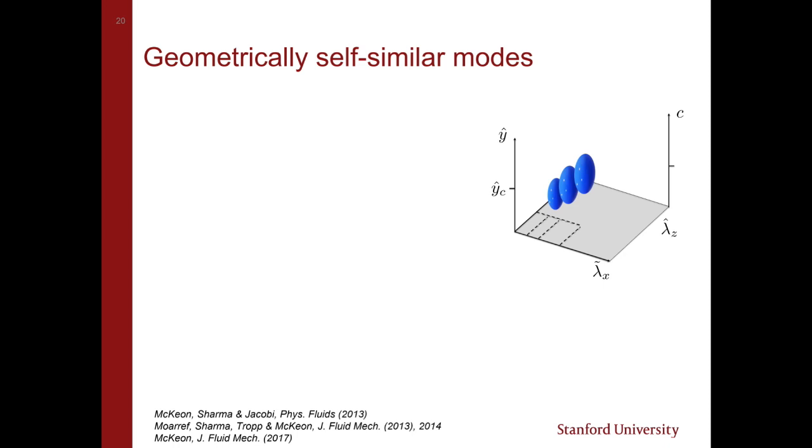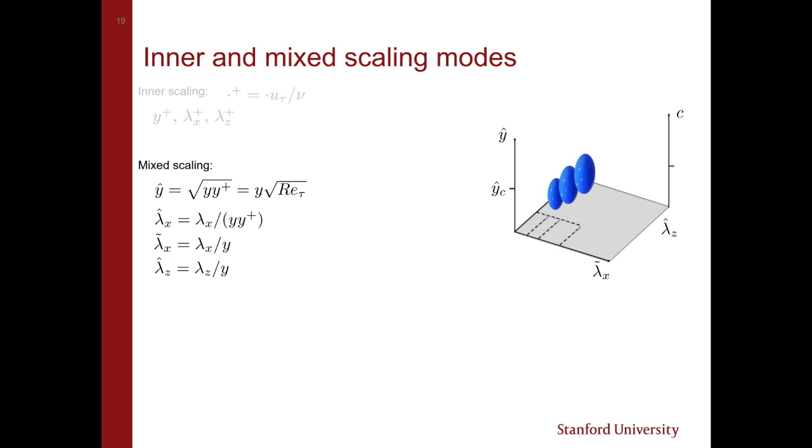They are geometrically self-similar. If I have a logarithmic mean profile, I can define families of these modes such that if I know what's going on at one particular wave speed, I can tell you exactly what the mode shapes are going up this particular scaling, and this tilde scaling, which I've lost here. Let's go back here. Tilde scaling, hat scaling is these two.